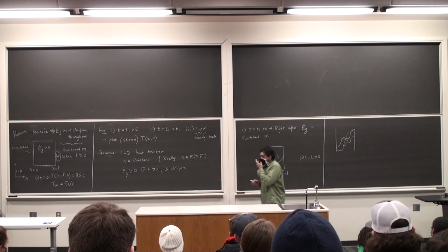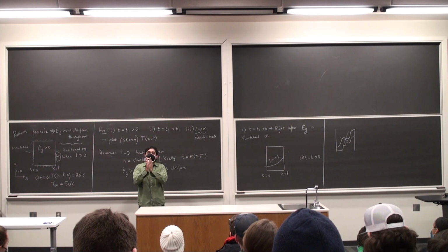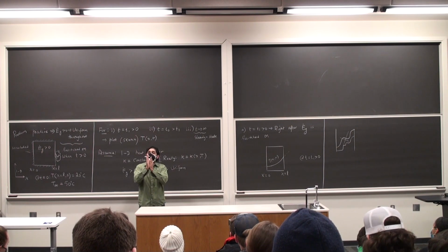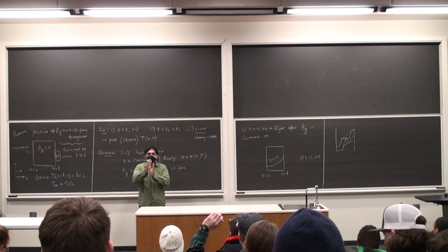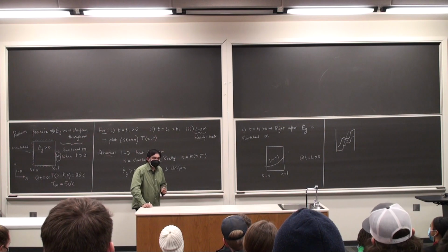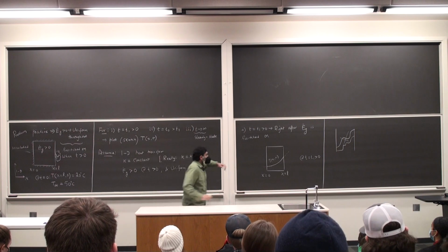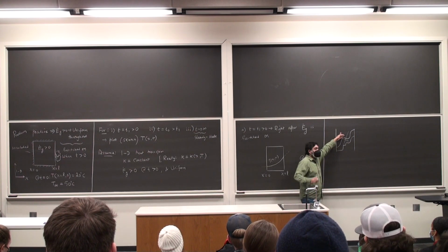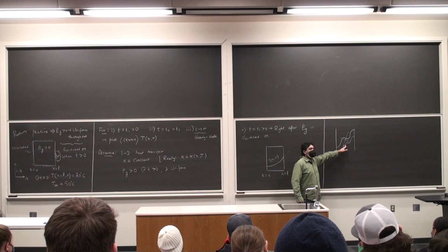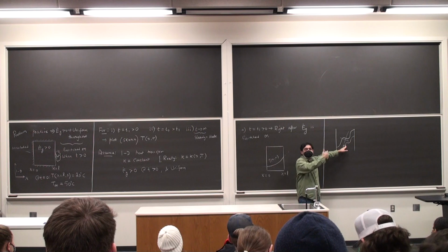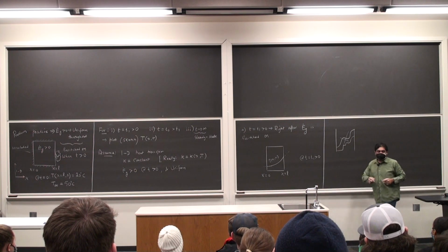And you want to be careful. If I have two dissimilar materials in contact with each other, at the junction of the dissimilar materials I can have a discontinuity in the slope. If heat generation was dependent on position, you could see graphs that look like this, or if your thermal conductivity is a function of position as well. But typically these things don't take place unless you have different thermal conductivities, different materials within the same wall, which you will have in your first homework problem next week.